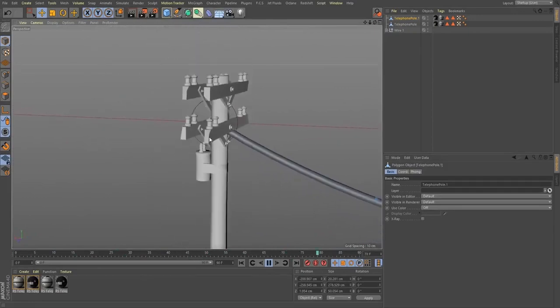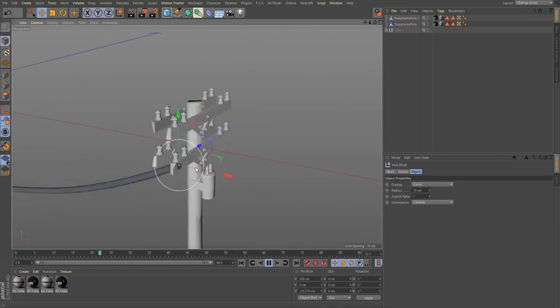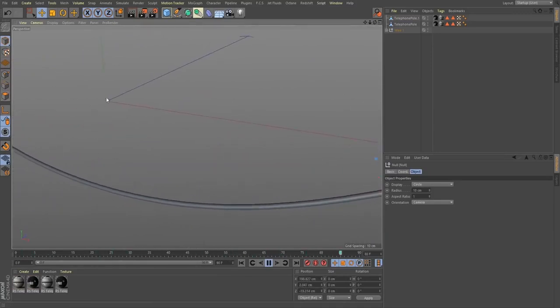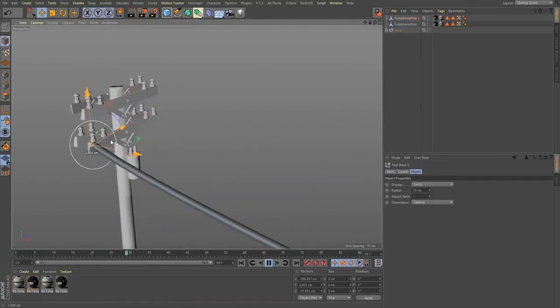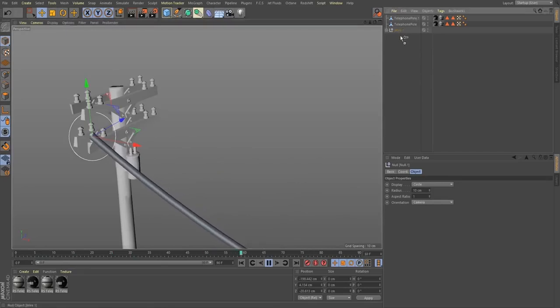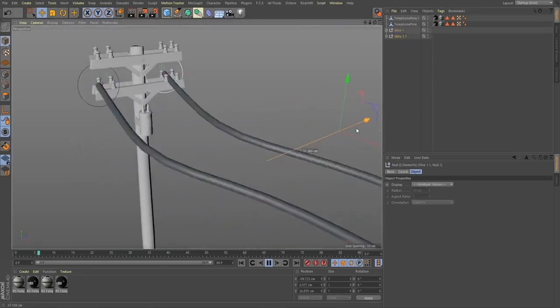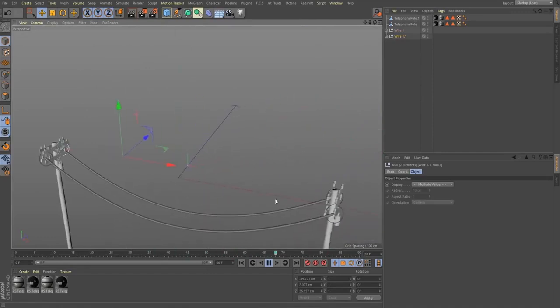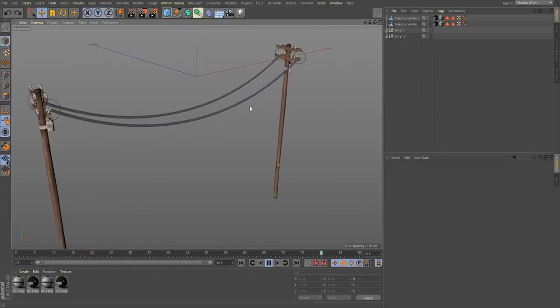I don't even know what DSL is, but we can loosely maybe put this null on one of these little things and come over to the other side and do the same thing. And whenever we're ready, we can grab this wire and just control drag it. And now we have a second copy that we can put anywhere else on this pole, and it's super quick to just iterate. Another fun thing we could do is maybe have one of these wires break off.